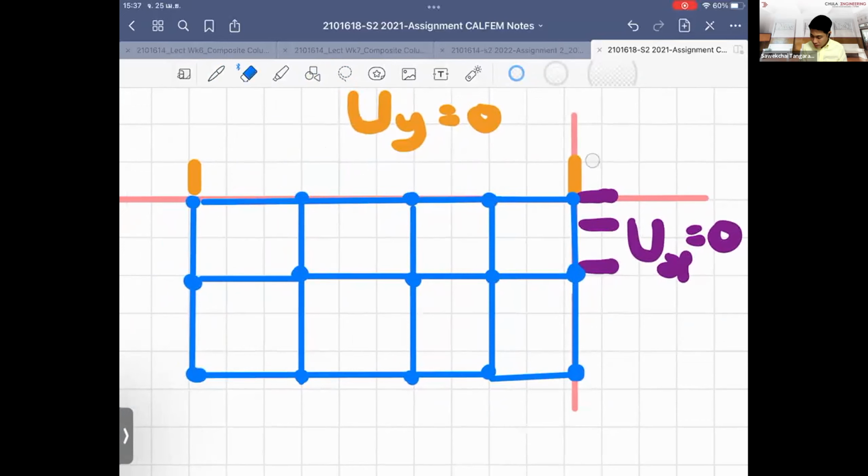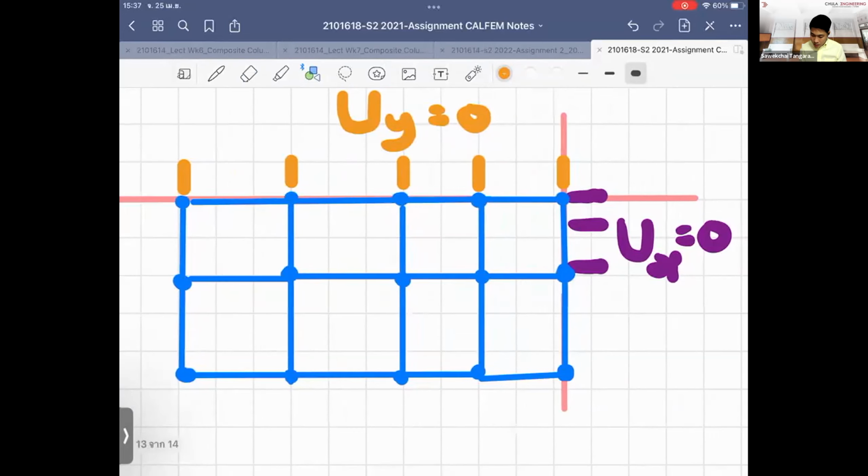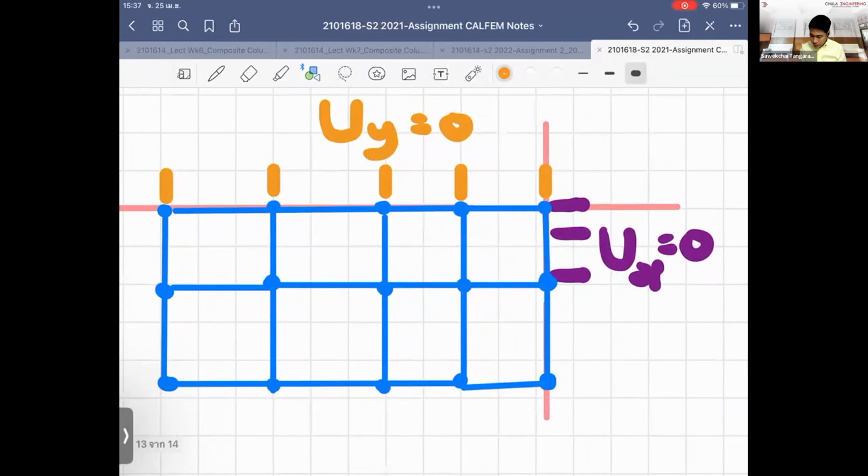And we put the boundary condition only on the node, saying that we want to allocate the restraint at this node and in this direction. Similarly for the restraint on the other side, so we don't need this anymore, and remove this.